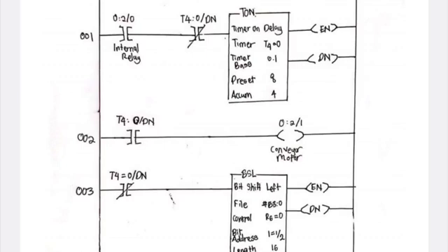So when the bottles detected by the proximity sensor are more than 7 steps from the capping machine, it will operate based on the bit shift register. When the accumulated value is between 1 to 5, that is when the conveyor is stopped for a second and the timer is at 0.5 seconds, which is the time required for capping a bottle. Next, we'll go to the capping machine.